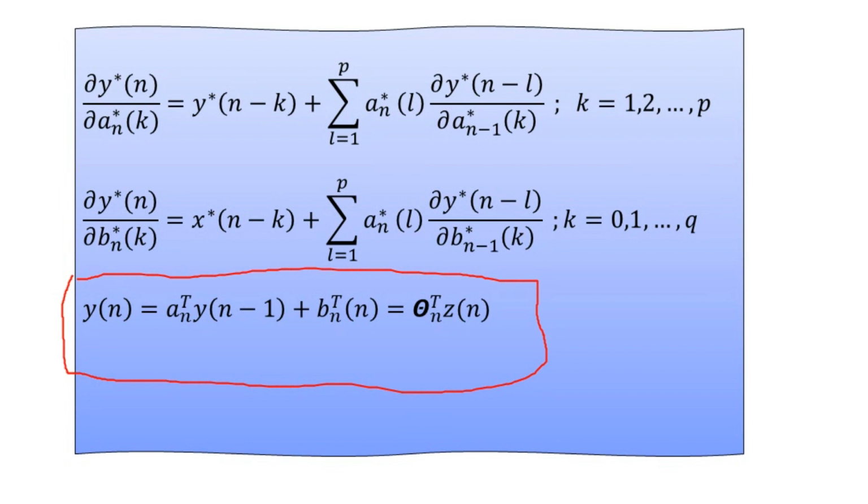As our current topic is adaptive recursive filters, as I have already made clear, whatever we have learned so far in this chapter was concerned with the design of finite impulse response filters, which we can treat as the non-recursive type filters. Here we are making use of the popular LMS algorithm for the adaptive filter design, but this is for the IIR case, that is the recursive filter. Up to this equation the derivation should be made if the question is like this. So this is the important equation for the current topic, adaptive recursive filters.